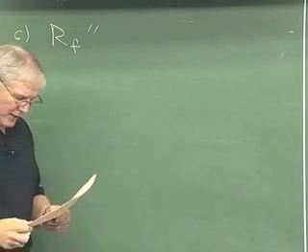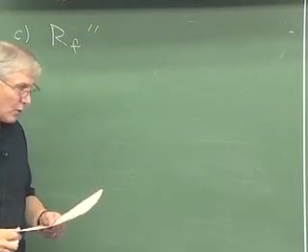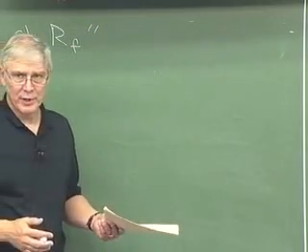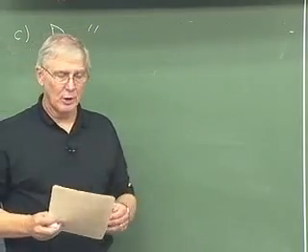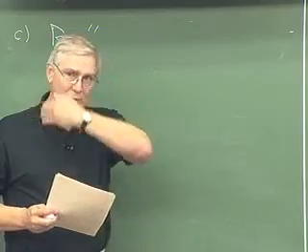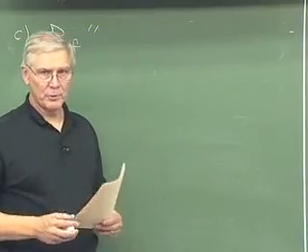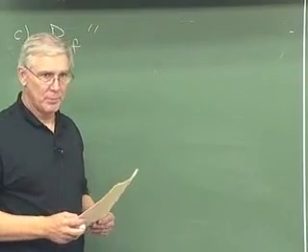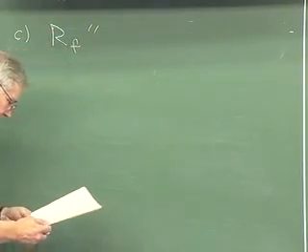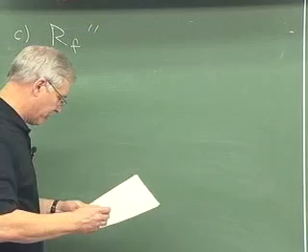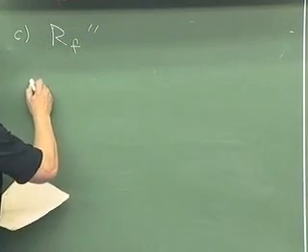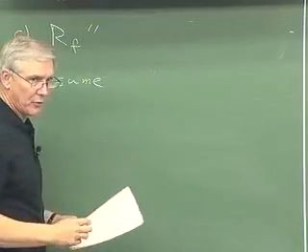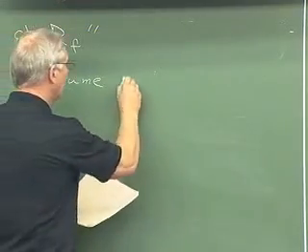Okay, in order to get the fouling factor, we can use the expressions that we've already developed. We know the actual UA from the experiment. We know the theoretical UA that we just calculated. So the difference between the inverse of those two would be the fouling factor. So first of all, as a first approximation, let's assume that the fouling factor on the inner surface and the outer surfaces are the same.